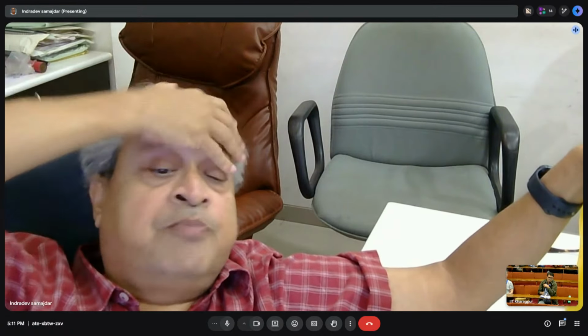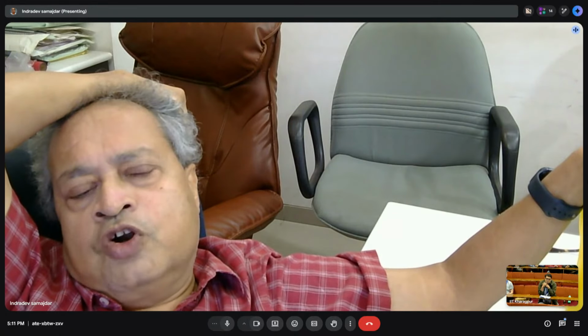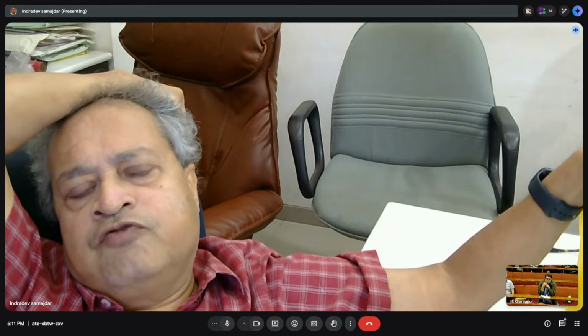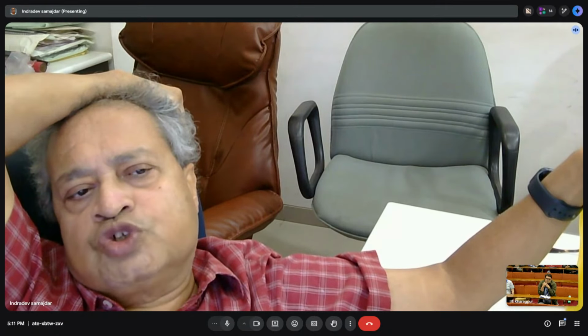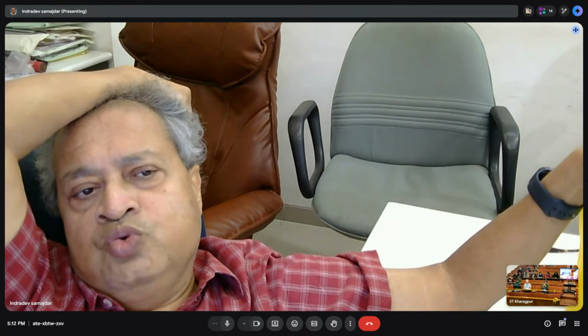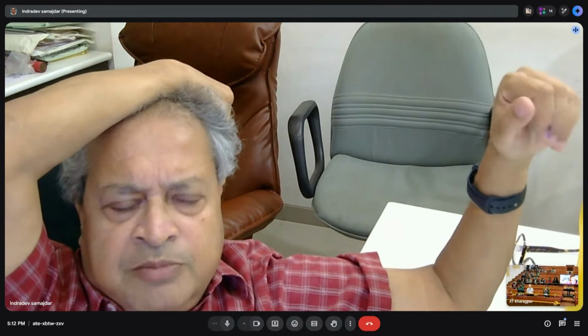More of a micro-Laue in multiple planes. It's easier. Number two, the primary difference is X-ray diffraction for texture, stress, orientation, and so on. The best which you can do, what I know of, is what the Rizzo guys were doing at 5 micron spatial resolution. Tomography, you can go to nanometers, but not for these measurements. Electron diffraction, on the other hand, you can do HR-EBSD at about 20 nanometers. TEM can be 1 nanometer or lower.